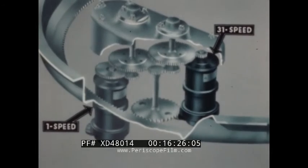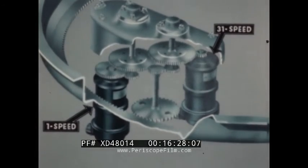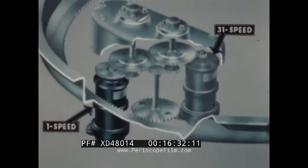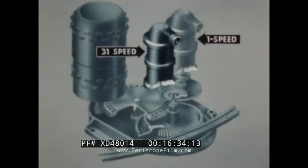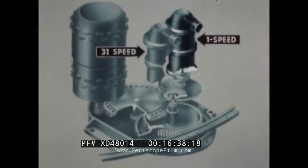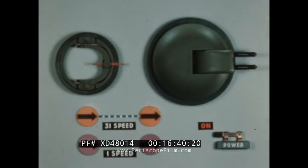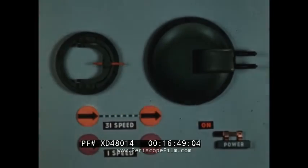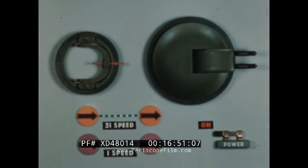To avoid this, another Selsyn transmitter is geared to the sight at a ratio of 1:1. And another receiver is geared to the guns at the same ratio. These Selsyn units take control of the system during large misalignments. Wires connect these one-speed units in the same manner as the 31-speed units.